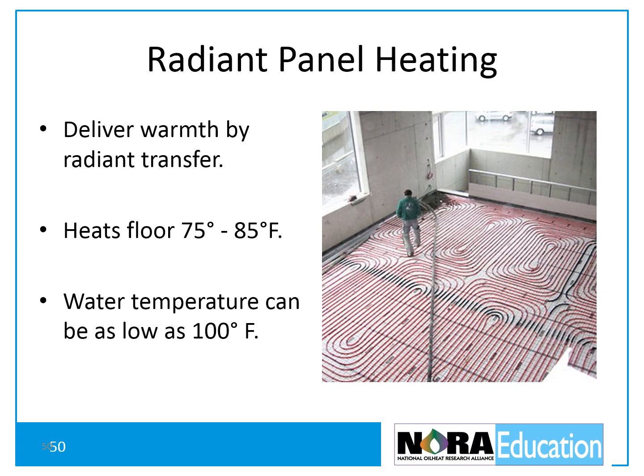Mixing devices blend return water from the radiant panel with boiler water before sending it through the radiant panel system. When a mixing device is used, there must be a circulator after the mixing device to ensure flow through the radiant panel.